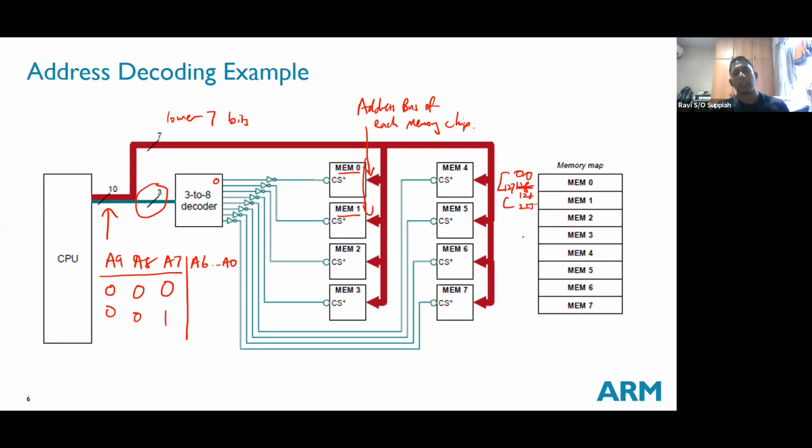So you can see that by doing this approach, at any point of time, I activate a particular memory chip on my memory map. This memory map is similar to what you have for your KL25Z. Only in your KL25Z, you have different memory controllers, peripherals, everything inside that. Later we will have a look at that. But this is the same approach that chip designers take when they want to design a new microcontroller.